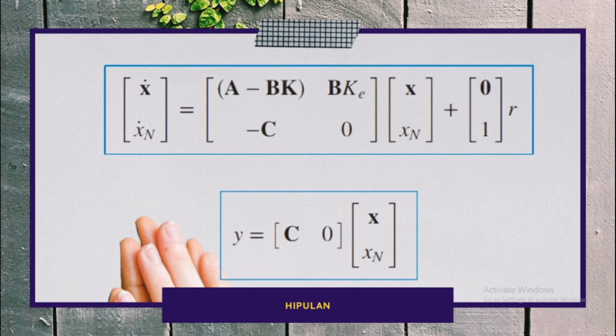Recognize that we now have an additional pole to position. So the effect of any closed loop zeros in the final design on the transient response must also be considered. One possible assumption is that the closed loop zero will be the same as those of the open loop plant. This assumption, which of course must be checked, suggests placing higher order poles at the closed loop zero location.